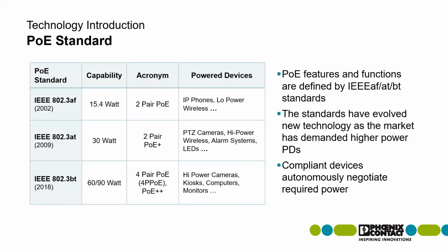When I said before it's kind of emerging, that's not a completely accurate statement. It's been around almost 20 years, but it's really being used more and more. The 802.3at standard, which we call PoE Plus, is what really started to make it a little bit more applicable in the factory space. Once enterprise had adopted it and was using it for 5 or 6 or 7 years, you started to see more and more folks using it within the plant floor. The standards as they're emerging are allowing more power to be delivered. More power means you can start to run more and more devices or different kinds of devices on there.